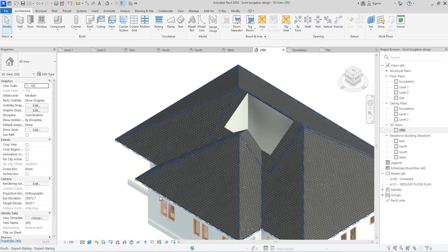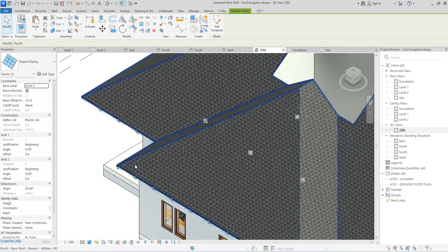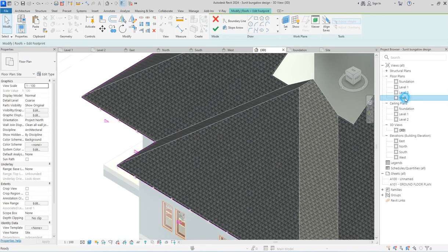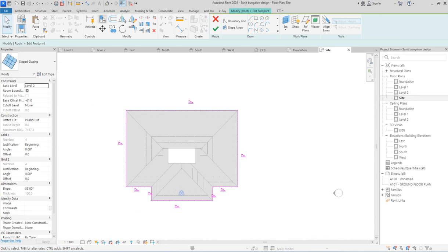But before then, I want to edit this one because I don't like the way it's showing outside. So you need to go inside. So edit the footprints. It's still your normal roof. So go to the sides. Then what do you need to do? Just offset it without copy. So click here and say offset. Let's say offset 200 all around. I don't want to copy it, so just let them offset inside, so that I don't want to be seeing that trusses at the glance of seeing my project elevation.